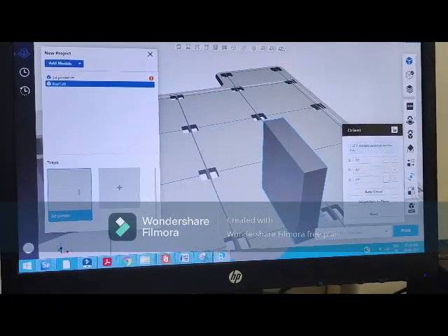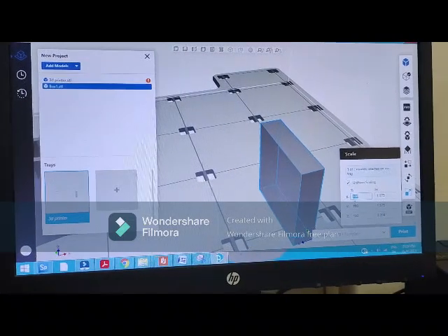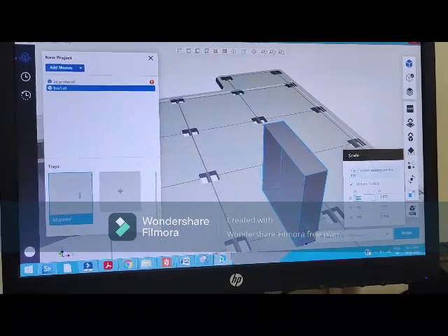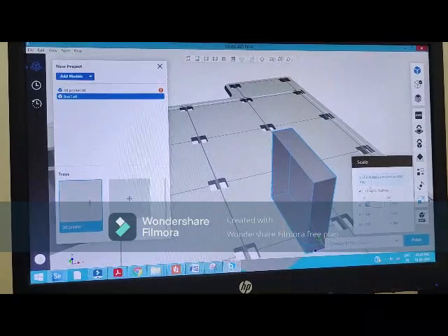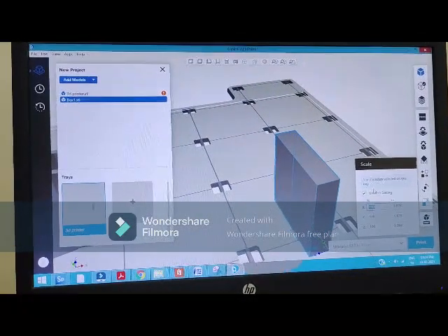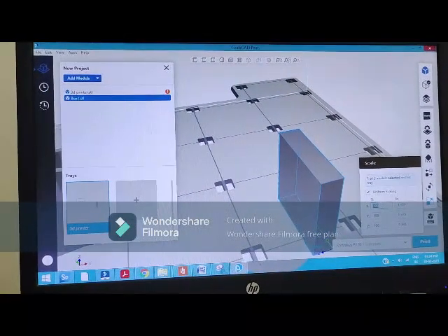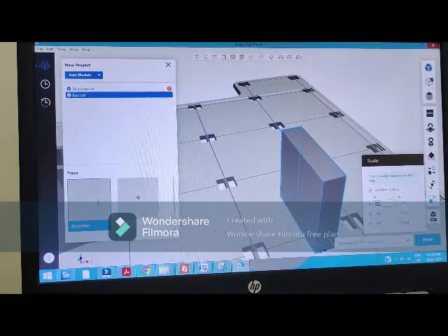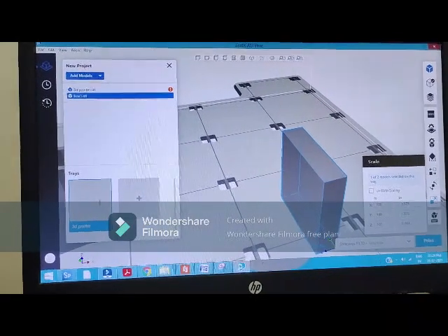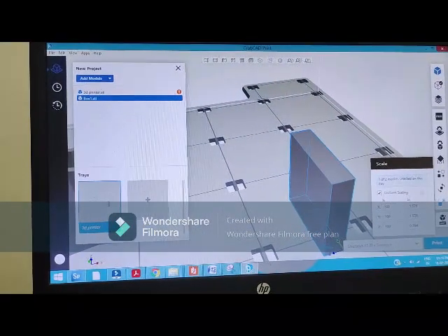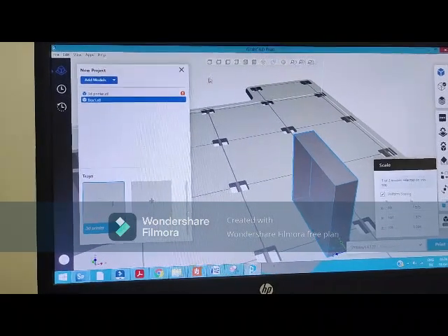Fine. We have this option, that is the scale. Similarly in the 3D Sprint software I showed you how to reduce the scale. So we have uniform scale. If I reduce only X using uniform scale, everything will change. If I untick it and change only X, only X will change. So these are the things we have here. Fine.